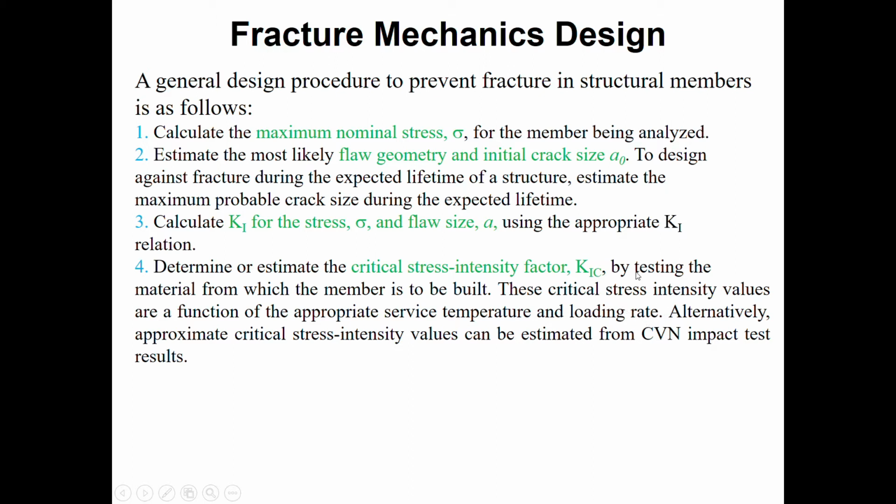What they mean here is that they already give you some kind of value at the appropriate service temperature at which we want to operate the design. So we need to use that value so that it will be suitable for the design temperature. Alternatively, appropriate critical stress intensity values can be estimated from CVN impact test results.